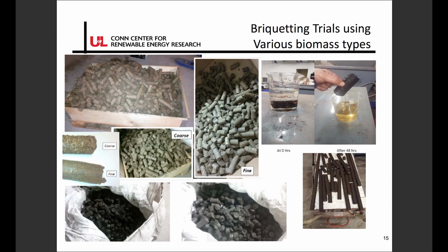The key to making these torrefied solid fuels, drop-in fuels, is the test over there in the corner. This one here, the biomass is hydrophilic. When you densify it, it cannot withstand water. It cannot be stored outside. Whereas coal in a power plant is stored outside, and it has to be a drop-in replacement for coal. That means it has to be very hydrophobic, very strong, and not dusty. And that's the kind of product we made.